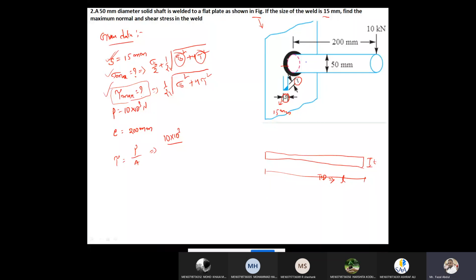I'm opening this black color welded portion now, this shaded portion I'm opening here. So now we can easily calculate the area. The failure area for this figure is pi d into t, where d is the diameter of the rod and t is the throat thickness. Okay. Now pi into d value, how much given in the question? D value is 50 diameter.